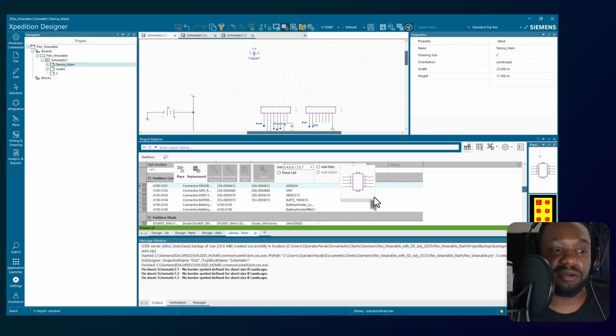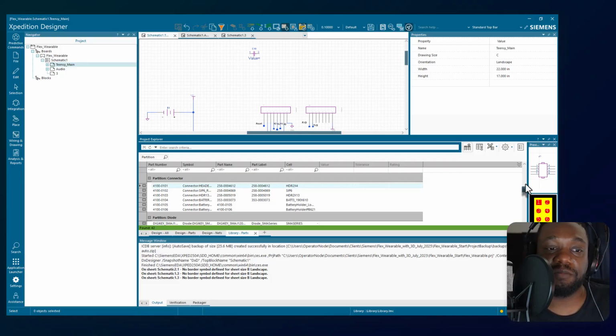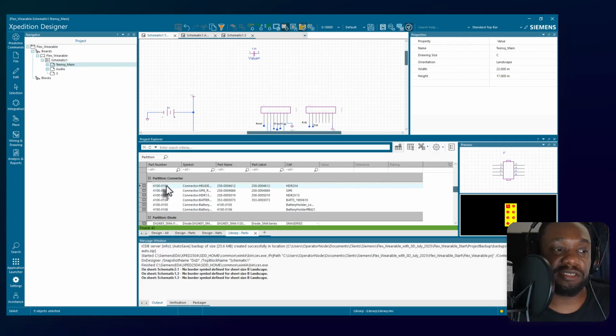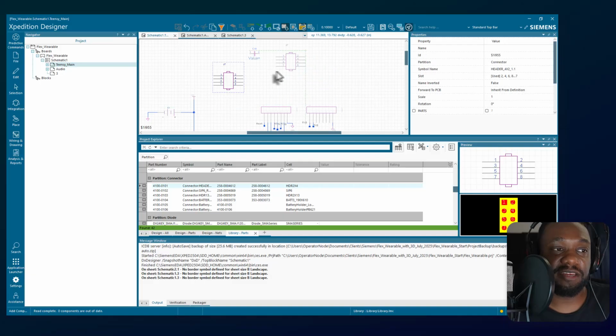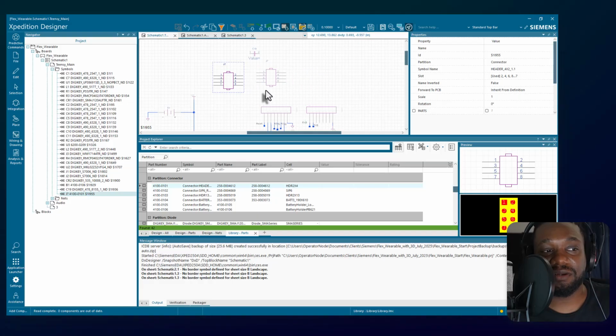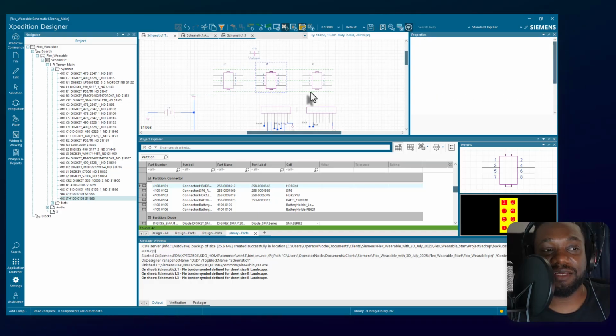And then you click on the down arrow and you can see the preview of the part along with its schematic symbol and the PCB footprint. The view is a little primitive, but that's okay. At least we could see the part, and this may pull from some database or whatever, and you click and place it. So I like that. I also like that the part stays attached to your cursor and it has alignment options, so you could line these up.